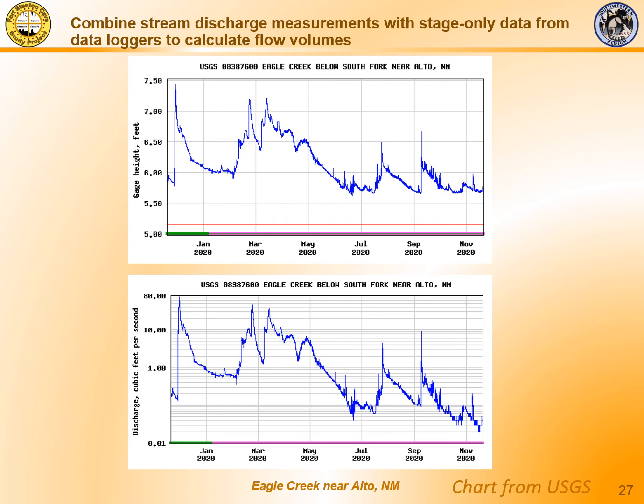Well, discharge measurements are very labor intensive and time consuming, and you only have a few of them. But if you build a successful stage discharge curve, you can go from stage to discharge at 15-minute intervals. So it would be possible to know, if you wanted to know how much water was going down the stream at any time, or the total amount of water that has gone down the stream in a particular interval of time, you can make that computation.